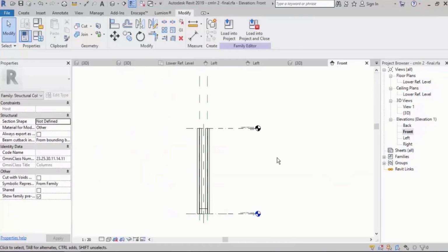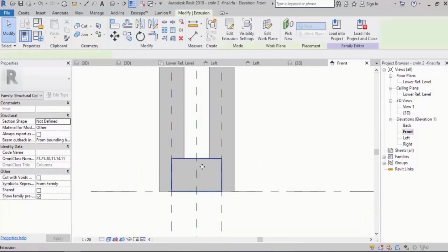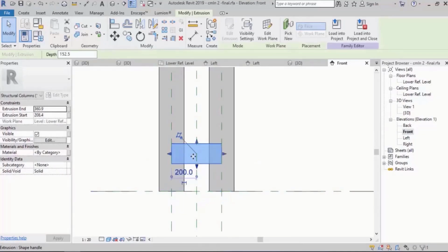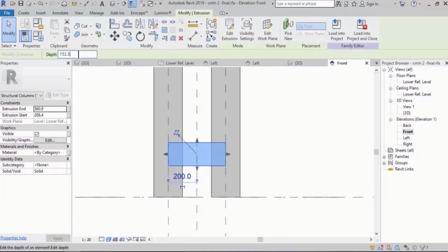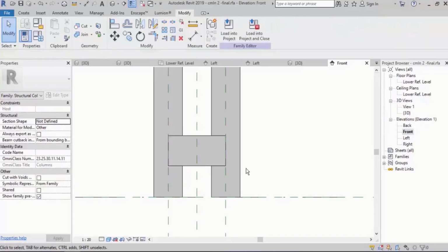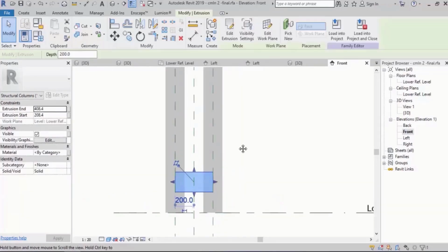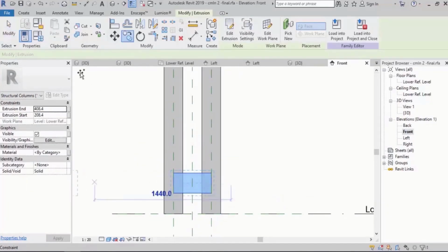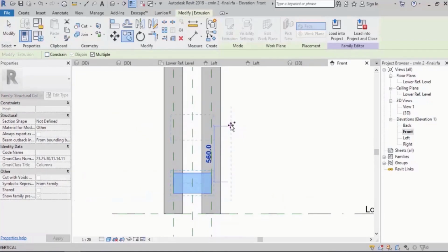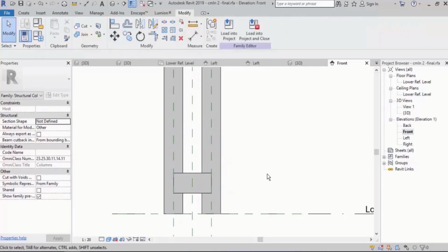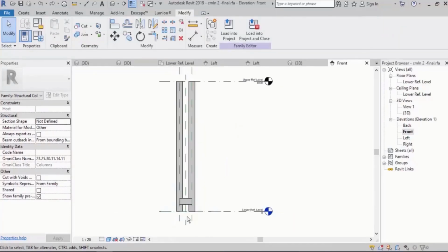And all that. Now let's check it out in the elevation. In the elevation, for example, the sheet we placed here, we want it to be 20 centimeters, the height, for example. And I want it to repeat with a specific distance. For example, each 20 centimeters, it should be repeated. Or let's say 50. Every 50 centimeters, it should be repeated. Now, when you want something to be repeated, what should you do? That's right, you need to array.